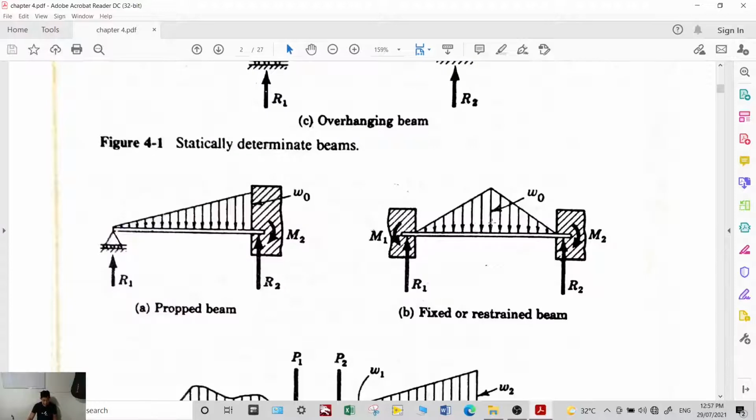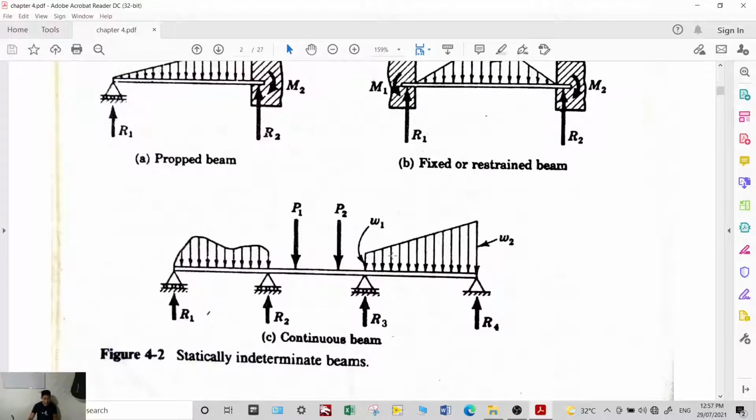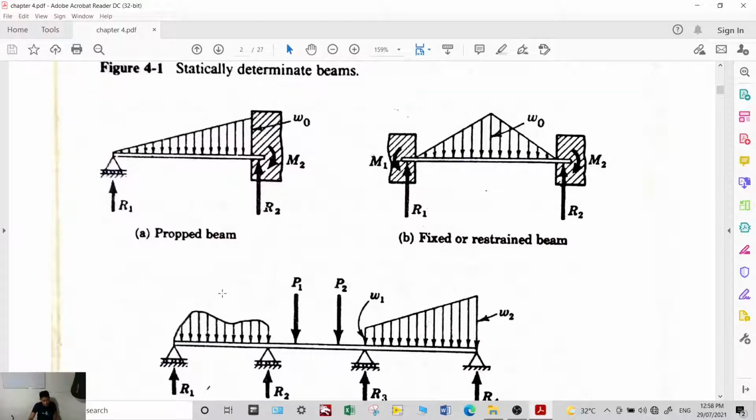This one is also triangular loading. This one is trapezoidal loading, a combination of uniform and triangular, or it can be broken down into rectangular and triangular. This one is what you call non-uniform. For example, when you pile cement and it is piled unevenly, there is a part that is heavier. That is non-uniform.